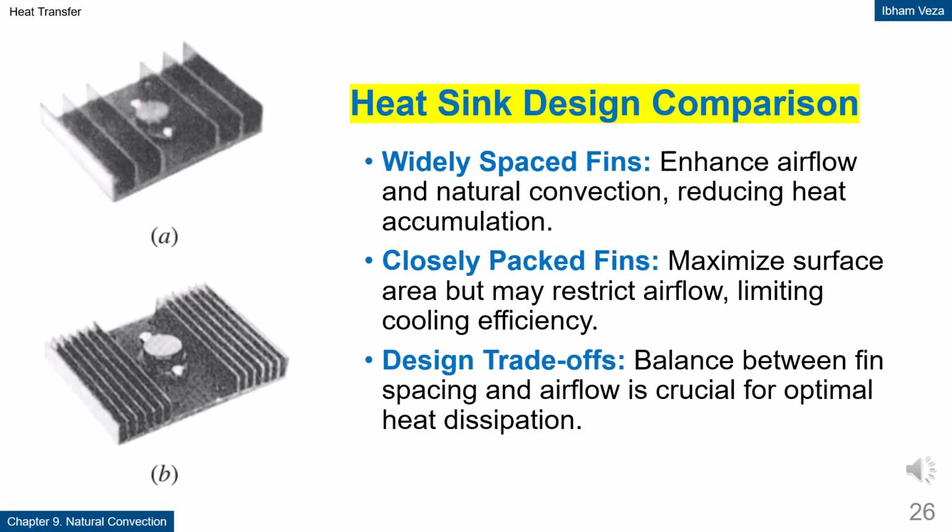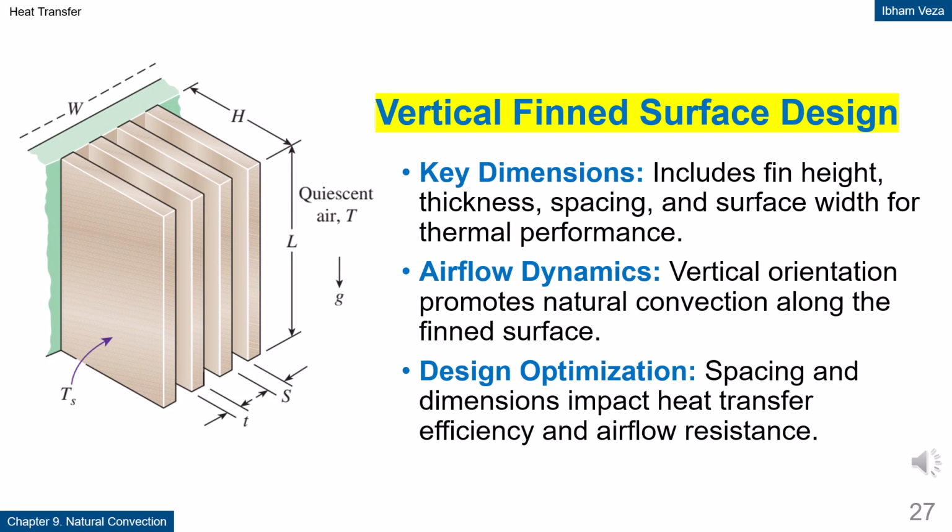Heat sink design comparison. Widely spaced fins allow air to flow more freely. Closely packed fins increase surface area but can restrict airflow. This flow resistance can actually reduce cooling effectiveness. Therefore, fin design always involves a trade-off between surface area and flow accessibility. Optimization does not always mean adding more fins.